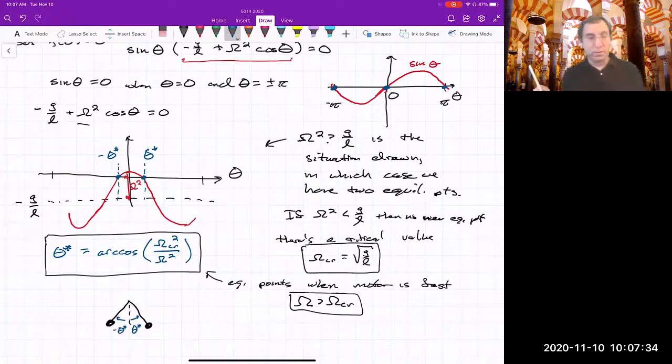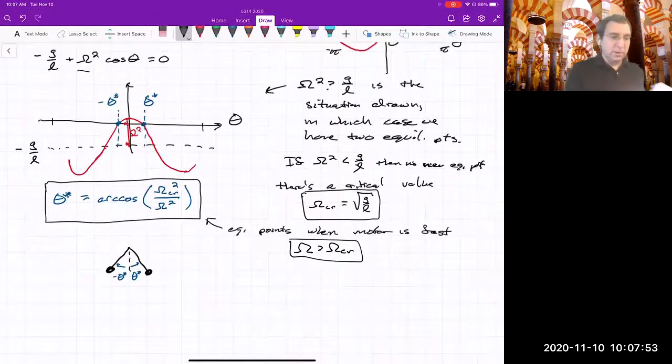It's an equilibrium point of the system. And that's sort of the nominal operating point. So the whole system of the flyball governor only works when you've got this moving out fast enough. So the motor has to be going fast enough.